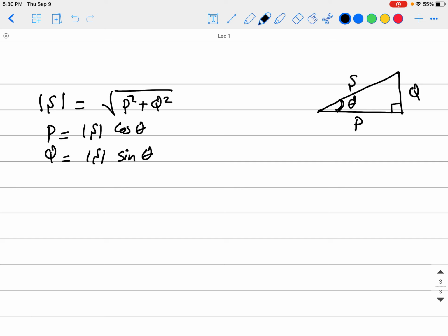And we need to mention that if you have this theta, which is a phase shift, the cosine of this theta from the triangle will be P divided by the magnitude of S. Okay, guys? And this is a very important value. We call it PF, the power factor. Okay? This value tells you, from the total power you have in the AC system, which is the apparent power, the S, how much of it is actually useful power.